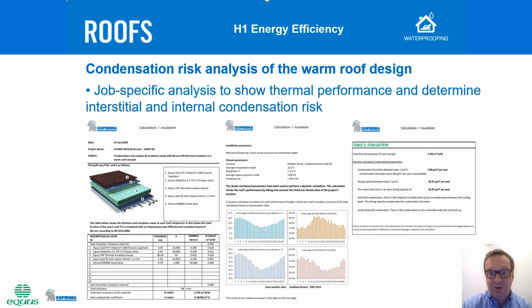Another engineering calculation that can be done is the thermal analysis. In this analysis, we are going to prove the performance of the roof, and more specifically the thermal performance and the fact that there will be no long-term condensation risk within that warm roof concept. As you remember, the goal of a warm roof is to keep the dew point out of the structure and to create a very long-performing roof that creates energy cost efficiency by energy cost saving for the building owner.